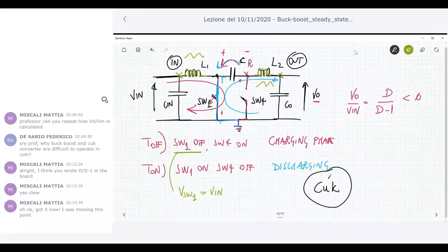So it's an advantage, because remember what happens in the buck boost. In the buck boost, the switches see V in minus V naught, which is a very huge voltage since V naught is negative. Now the switch sees only V in, not so huge as for the MOSFET you have to use in the standard buck boost. The breakdown voltage is reduced, which means that the R-on resistance is also reduced.